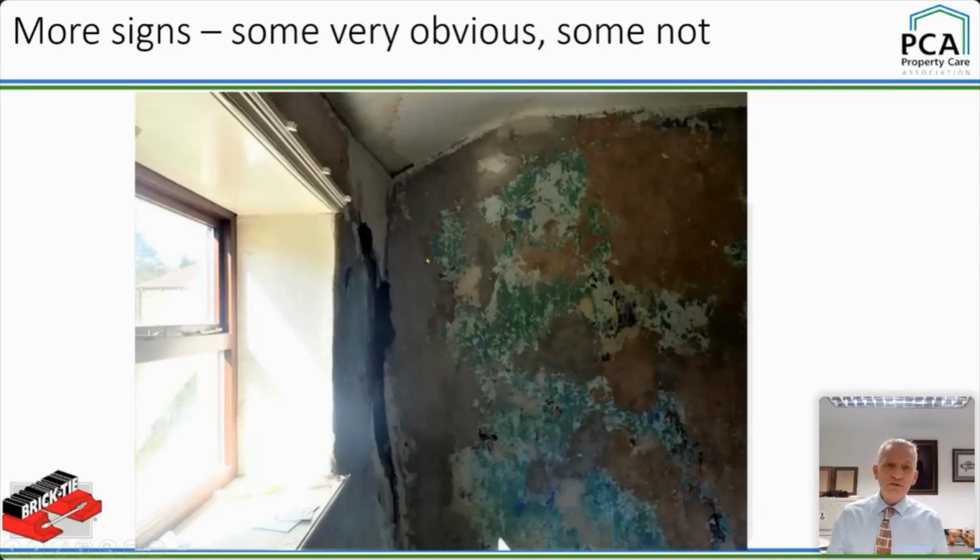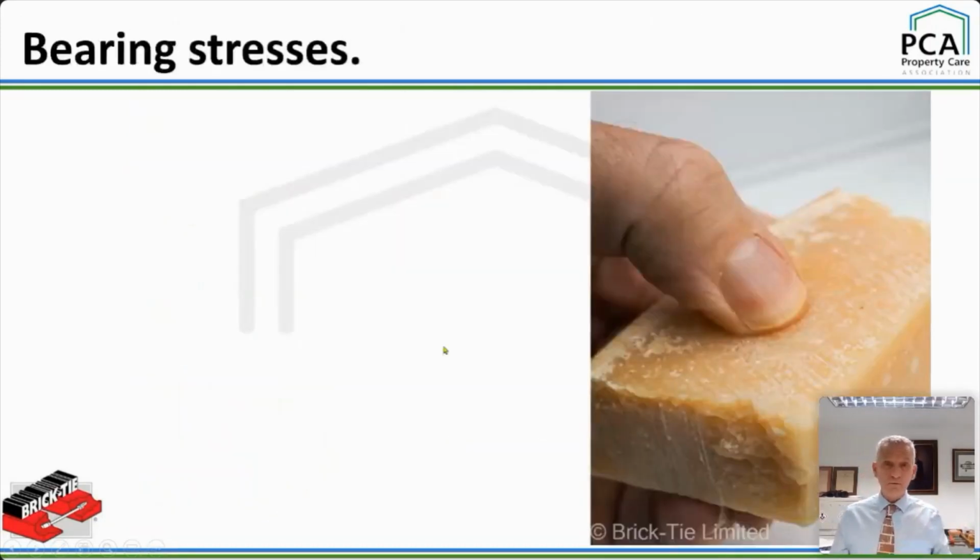Okay, so if you see that crack, you need to ask questions. If you see that curve, you need to ask questions and see what we can do about it. Because often when we hack off plaster in these old houses where there's been a hairline crack, there's a fist-sized crack behind it, full of newspaper. All right. Back to some